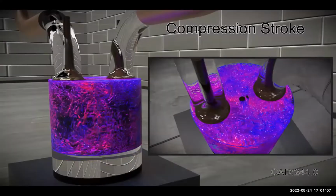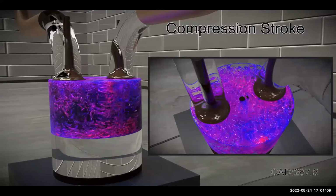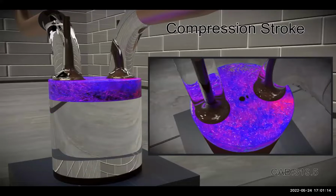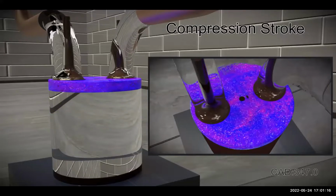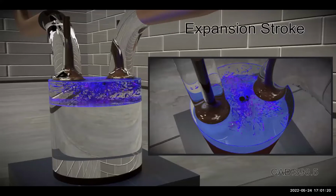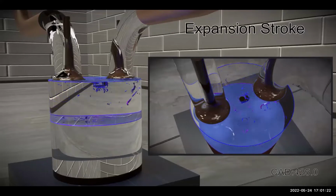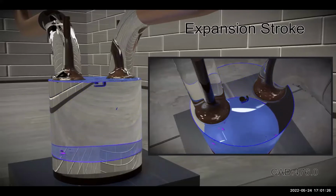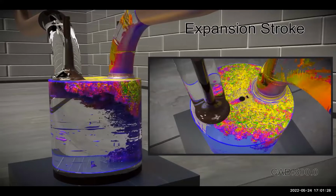During the compression stroke, the valves are completely closed as the piston moves up towards the top of the cylinder. This compresses the air trapped from the intake stroke and increases the turbulent intensity of the air. Compression is followed by the expansion stroke, where the piston moves downward, which increases the volume of the chamber. Here, a sharp suppression of turbulent kinetic energy reduces the appearance of vortex structures.